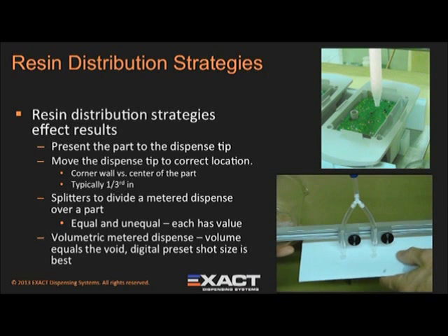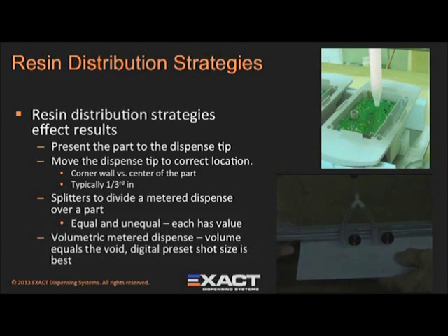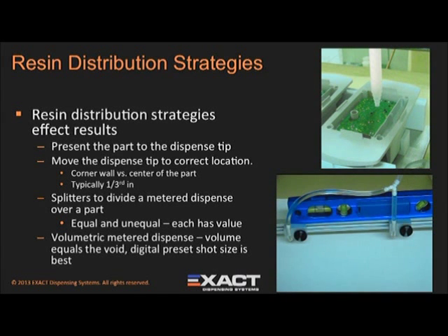If you know how much material is needed to give you good potting results, use of your exact volumetric dispense option to deliver only the required amount of material is a good idea.